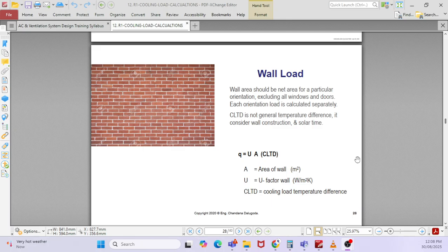No, go to ASHRAE, because if you go online, it is up to date. You will get all the values. For example, if you talk about UAE, Dubai, the local guideline will tell you that you have to use 46 degrees Celsius. But ASHRAE is updated as per local condition. Now it is not 46 actually. It is actually like 48 or 49 degrees Celsius.